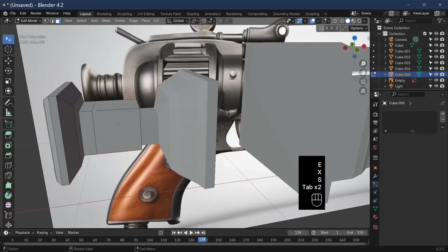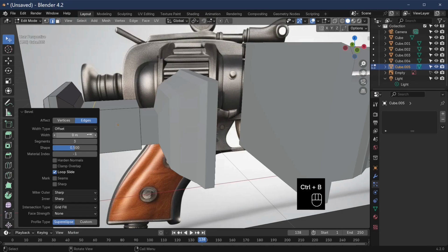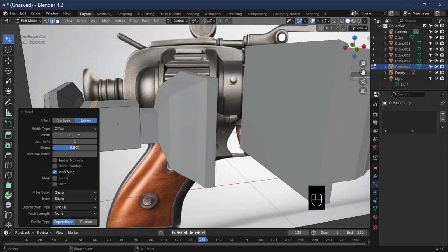And what we can do is we've got like a little thing there that's coming out, so we're just going to actually add a bevel on this. So select, press the Alt key down, Control and B, just to actually add it. I don't want 3, I want 2. Bit wider than that. Don't know why it's done 3. Let's take it down to 1. Just take it that little bit wider. I'm just trying to actually mimic this,